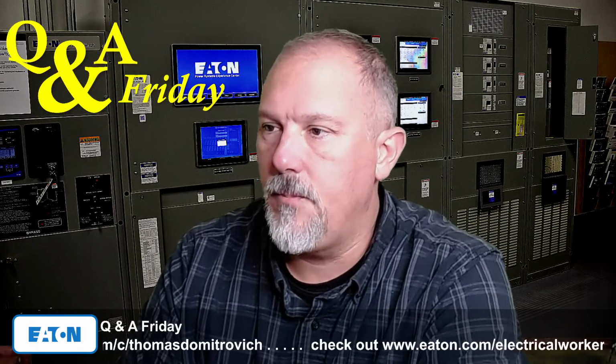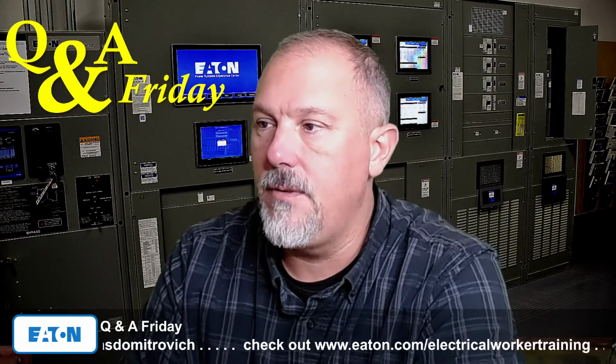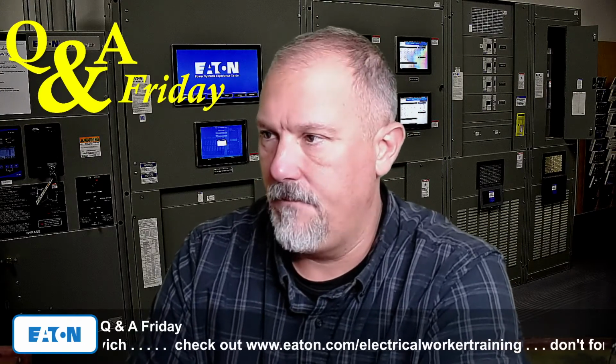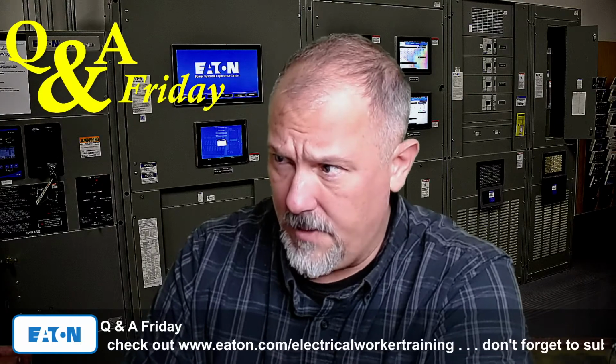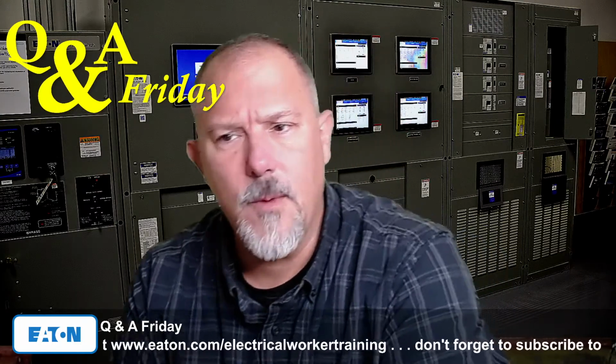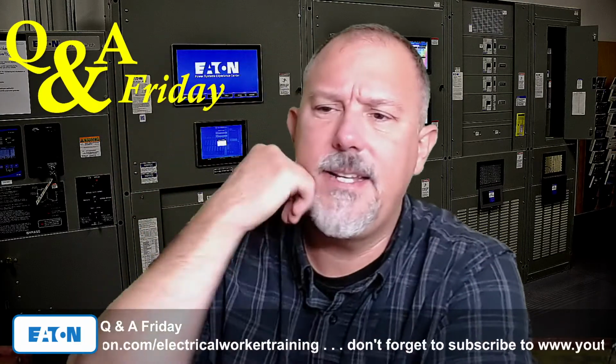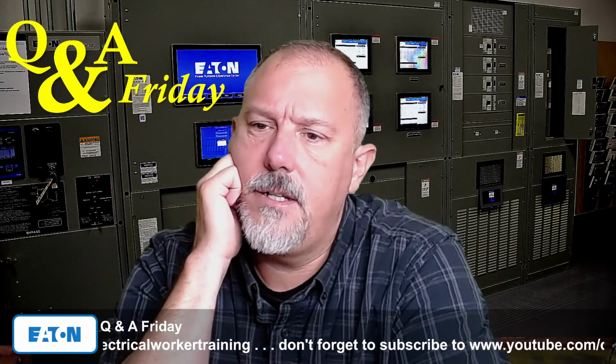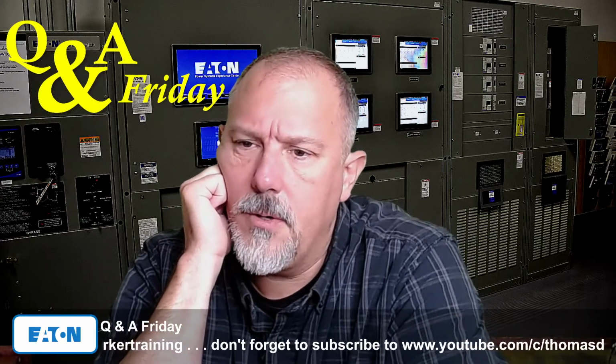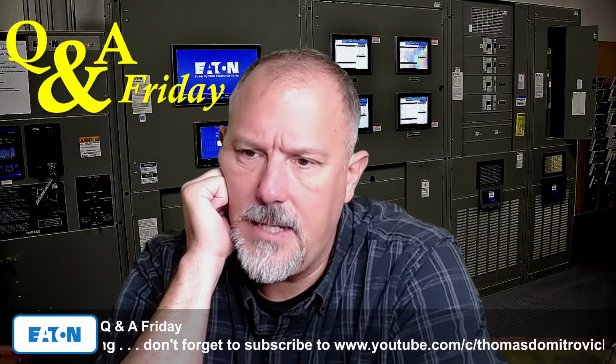The arc flash label shall be in accordance with acceptable industry practice and include the date the label was applied. The label shall meet the requirements of 110.21(B). So Ryan, you said your issue is that it requires a label per an industry standard. The NEC is an industry standard.